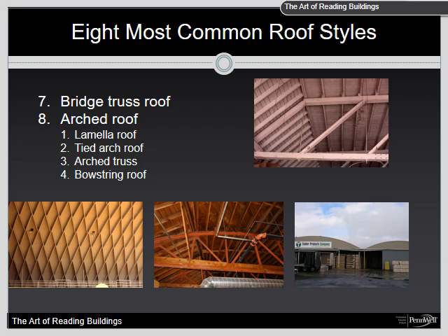The steel used for the tie rod is ductile, meaning it can flex and move as live loads are gained or lost on the rooftop. For this reason, the walls of a tied arch building are typically reinforced with a pilaster or buttresses where the arches sit.